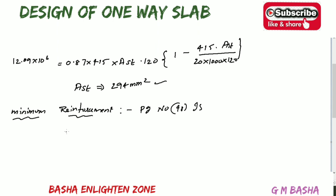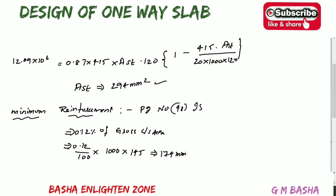So that will be equal to 0.12% of gross cross sectional area, that is total area. That will be equal to percentage, 0.12 divided by 100, into b and d. So b will be 1000 and d will be 145. Okay. So you will get 174 mm square. Means the minimum reinforcement required for this slab will be 174 mm square, but according to our requirement you will get 294.